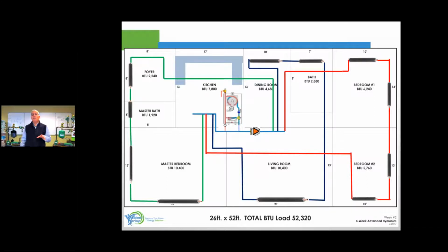How did I do that so fast? I divided 12,000 by 10,000. Or I just took the comma and moved it to the left one spot. So that's 1.2 GPM. I have to guesstimate how long that piping is going to be, all right? So from the boiler side, across, down, back around to the return. And my guesstimation for that was about 84 feet.